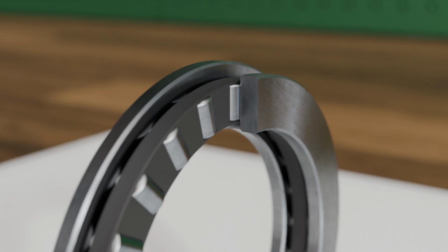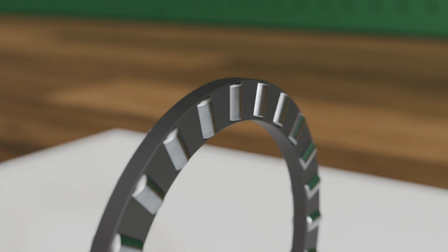These separable cylindrical roller bearings, due to their non-self-retaining design, also cannot absorb radial forces. Besides these complete thrust cylindrical roller bearings consisting of rolling elements and multiple washers, there are also simpler and more space-saving versions called thrust cylindrical roller assemblies. Thrust cylindrical roller assemblies consist only of a cage with fitted cylindrical rollers and do not include shaft or housing washers. They are suitable for applications where no separate washers are required because the adjacent components already serve as raceways. This allows for very flat and compact bearing arrangements.